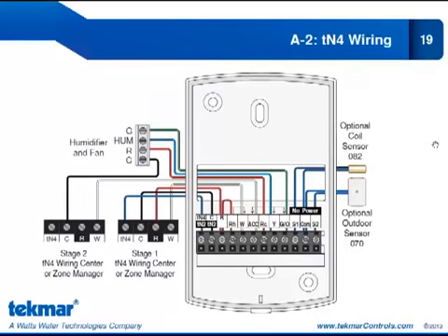We're going to look at the TN4 wiring only for this application because it does get repetitive, but we'll show you the slight variation if you're using a TN4 device. The first stage heat is still communicated with the tekmarNet, but now it's tekmarNet 4. So we have TN4 to TN4, C to C. Our R is coming into the R. We have a jumper R to RH, and then the W will come to the W on the TN4 control.